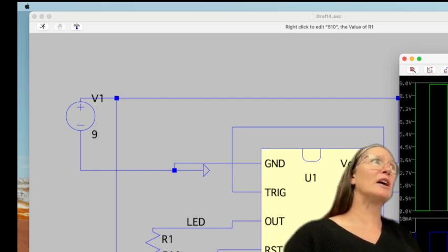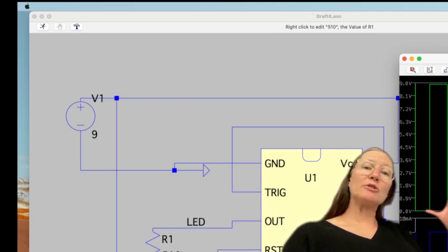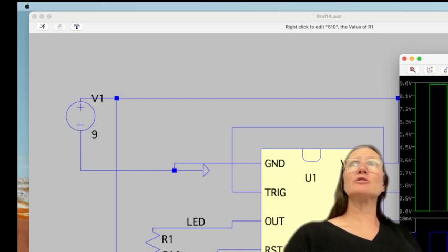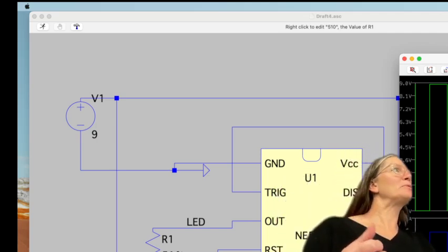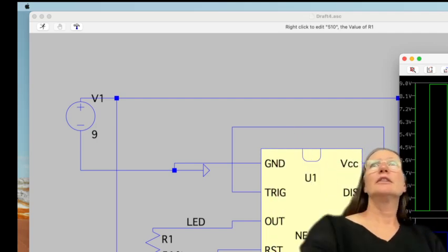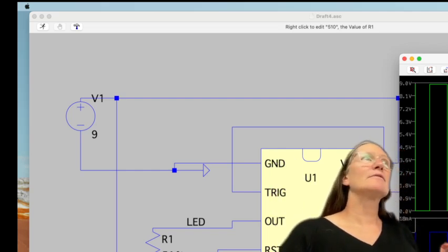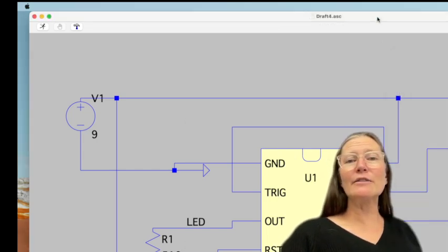What is the drawback of doing that though? Okay, so the voltage might drop a little bit more, but you have more current, which means you're drawing more power. So you're going to be consuming more power, which is going to drain your battery quicker. So you've got to decide: do I want it to be really bright, or am I okay with it less bright? That's your trade-off there. All right, make sense? Make sure that you can get this clock going.